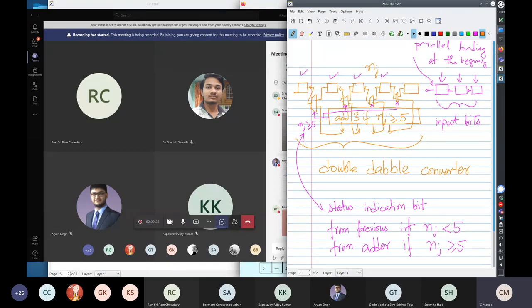You have a synchronous reset bit, right? You can do a synchronous reset of these flip-flops to 0. As such a shift register can shift, that is not the problem. But in this case, you have another circuit here, which looks at all these values. If these are unknown, you'll have a problem with this. The outputs will also be unknown.